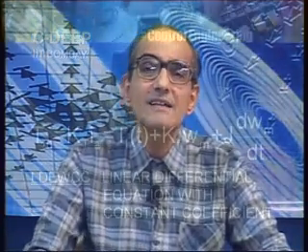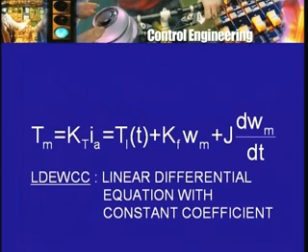Similarly, we could say that the load torque is also kept constant, let us say 30 Newton meters or whatever it is. Or we could allow, because it is more realistic, for the load torque to change. So we may consider that the load torque TL will be a function of time, and we could consider various ways in which the load torque may change.